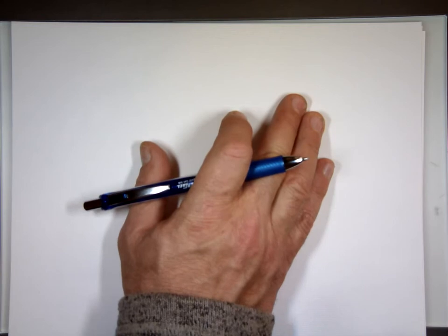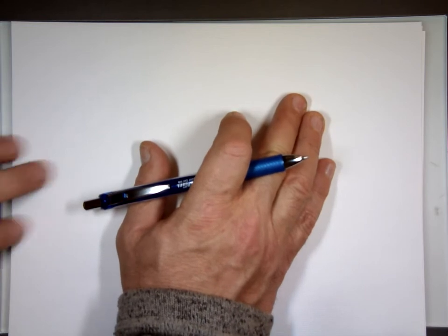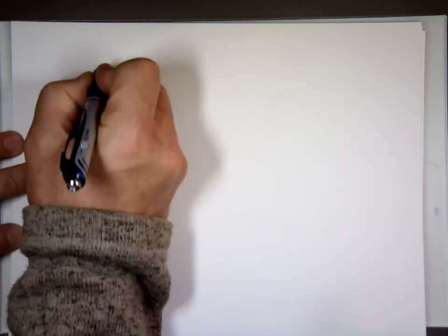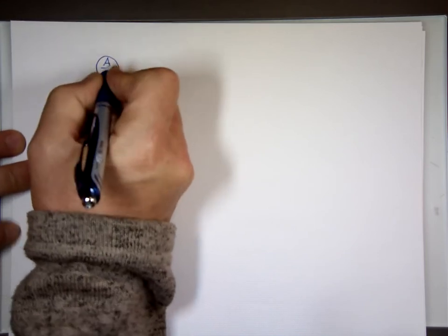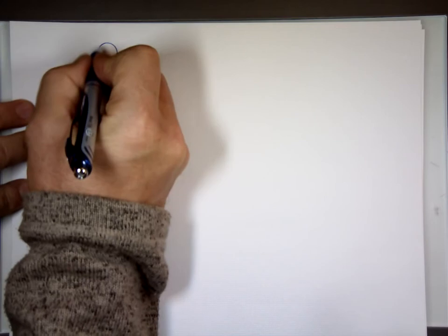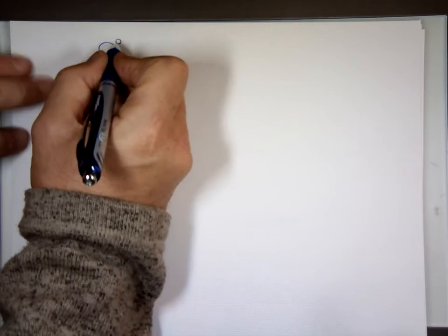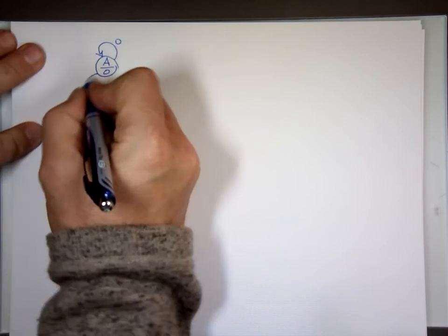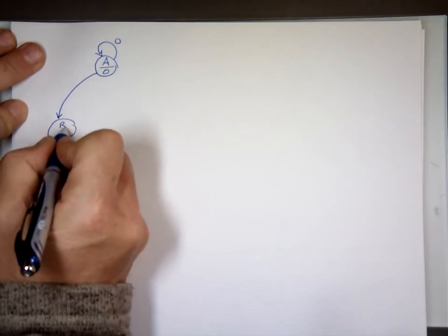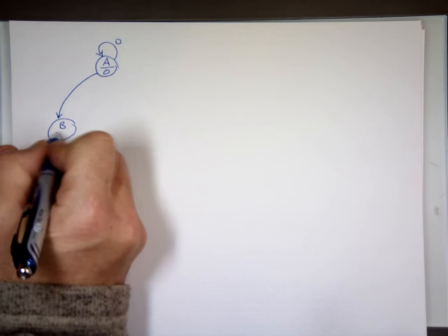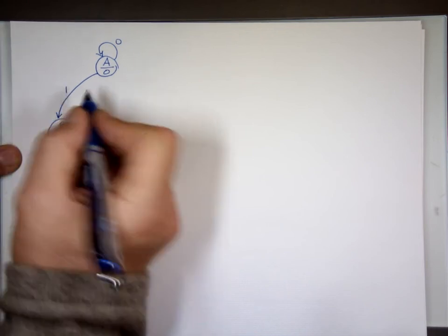And we have state A. I'll put 0 for that. When you put a 0, you stay here. When you put a 1, you go to state B. Your output is 0 at state B. You put a 0, you go back here.